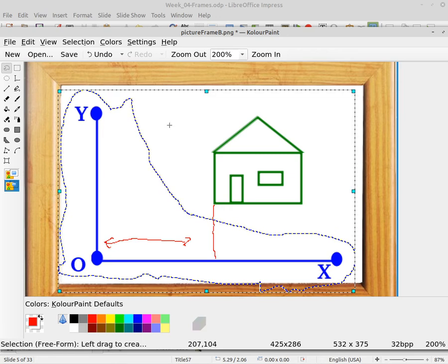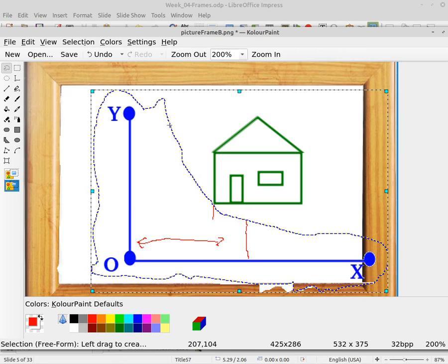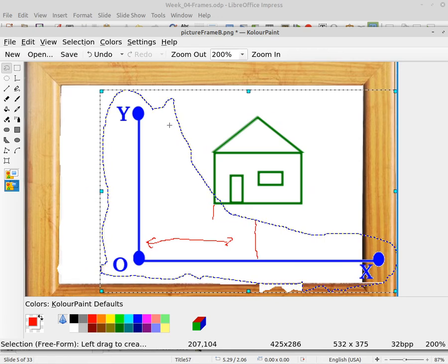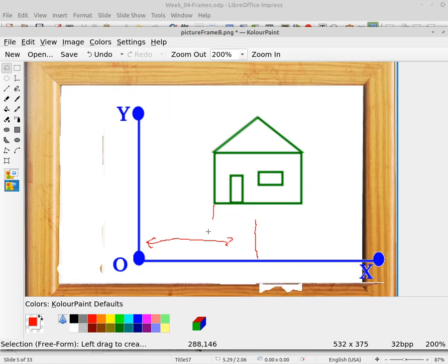We could shift this frame over that 100 millimeters or whatever it needed shifted, and then all the points within the program will be lined up again.